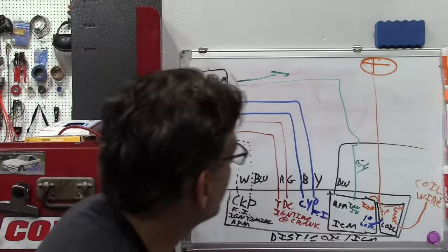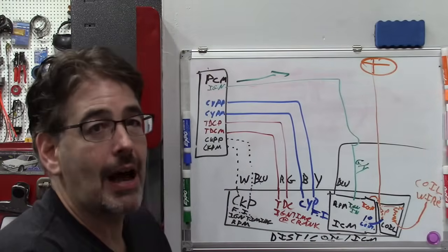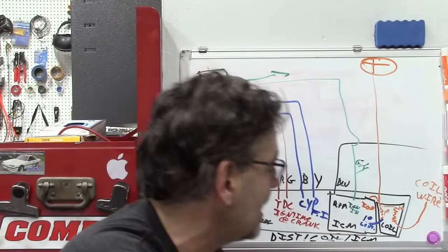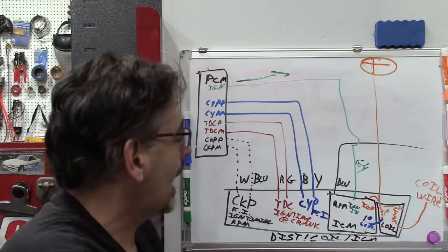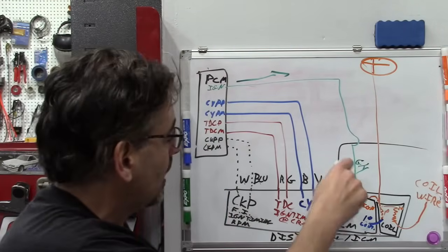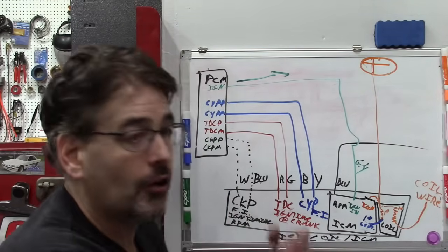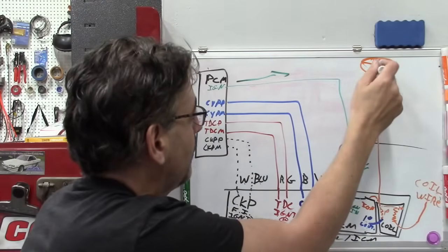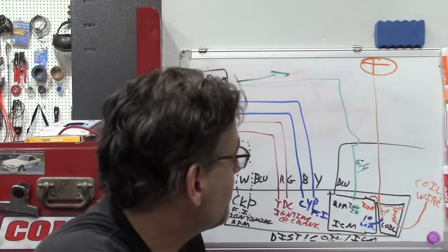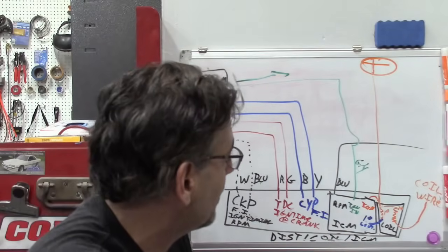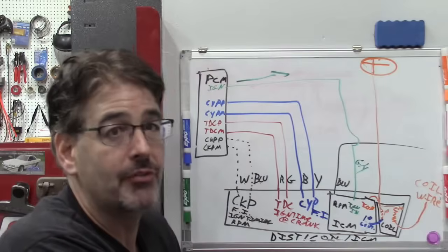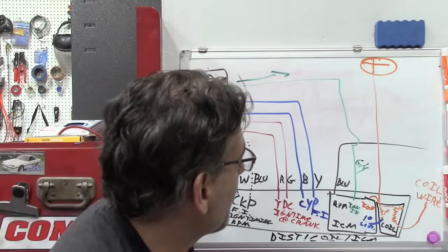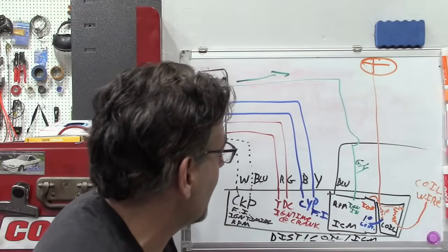But honestly, on any other car, if I test the ground and I put a signal into that coil, and there's also 12 volts to that coil, which I know there's 12 volts to the coil, that was the very first test we did. If I put that signal in with my test light like that and that coil doesn't fire, I'm done. That coil's bad. So if this was like a coil on plug on a more modern car or something,